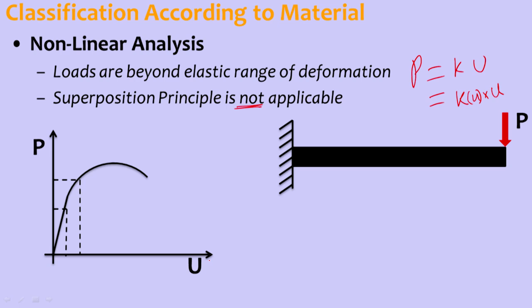In the horizontal axis is displacement, and the vertical axis is load. It is proportional only up to this level. So this we can call the yield force or yield displacement, uy. Up to that, linear analysis is applicable, and beyond that it is nonlinear analysis. As you can see, after yield, the slope of the tangent at every point is reducing. So that is considered in nonlinear analysis.